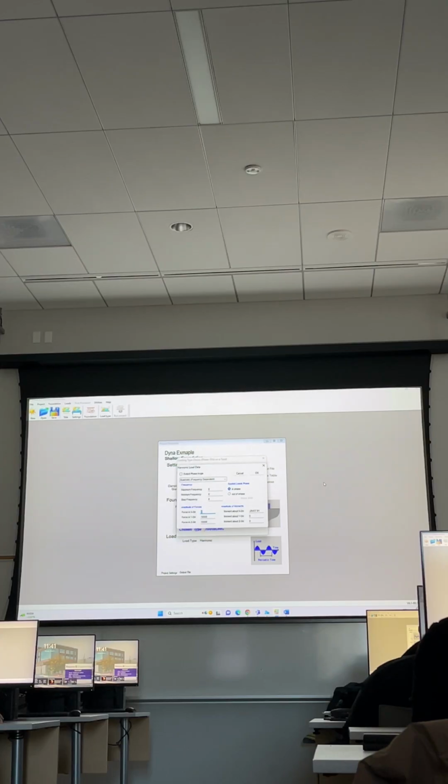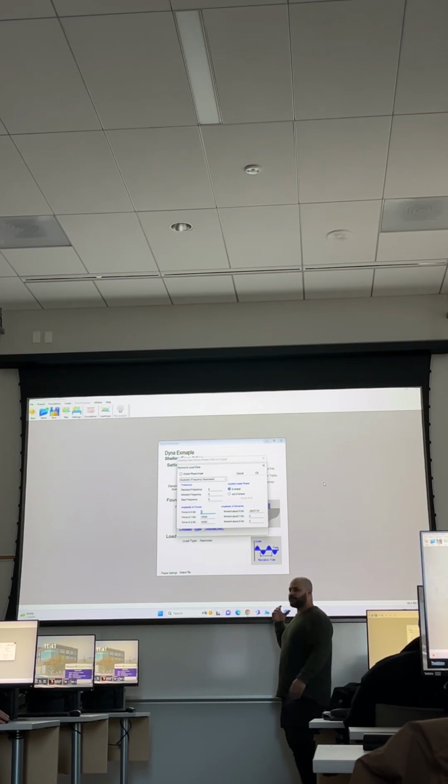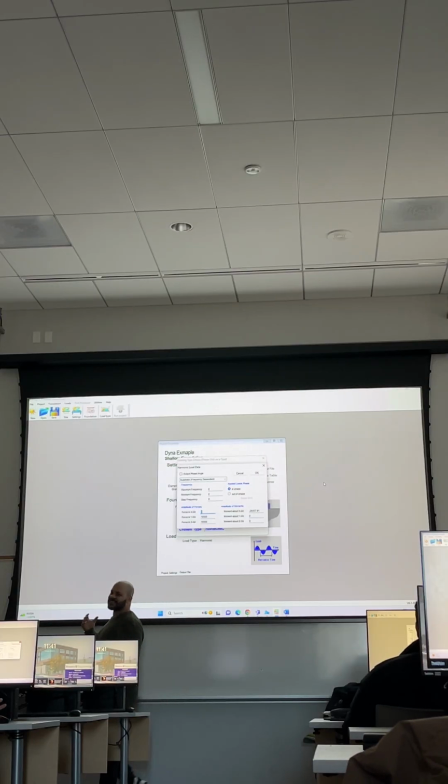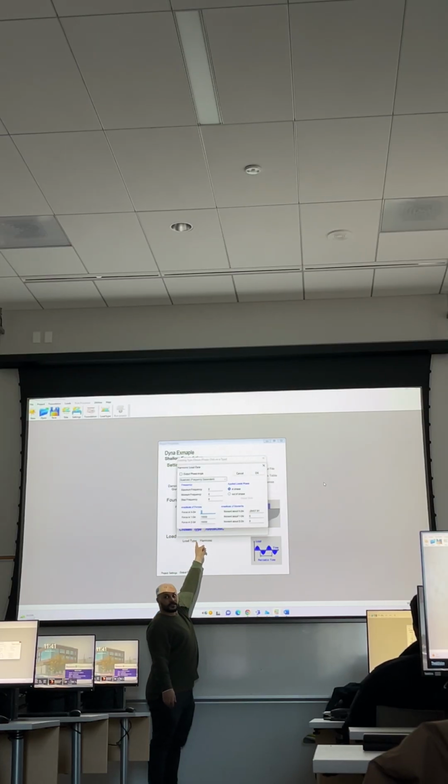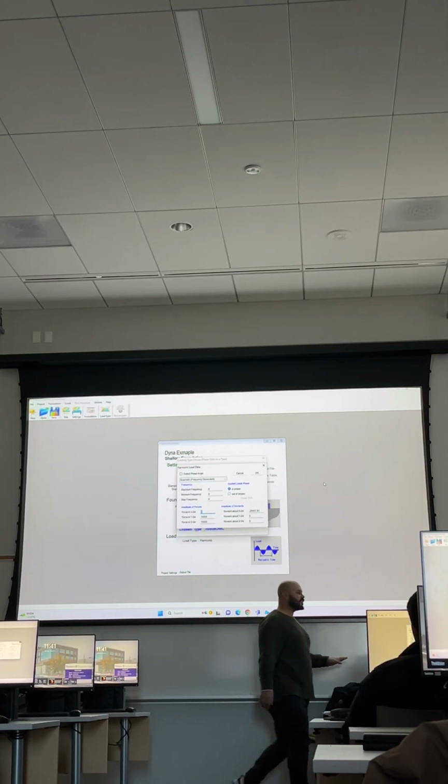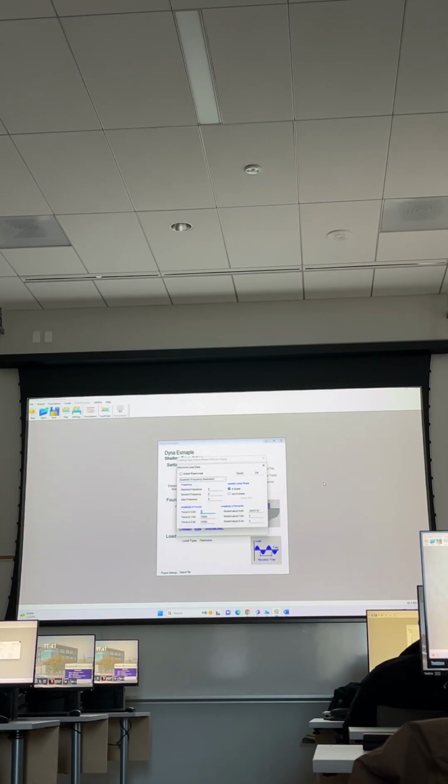Okay. You remember the force we defined in the foundation, we defined the force is 10 kilonewtons, which is 10,000 newtons, right? You will find the same value, the software brings it to you here. So we don't need to define the value of the force, but we need to define other stuff. For example, it will ask you about the frequency. What is the frequency of interest?